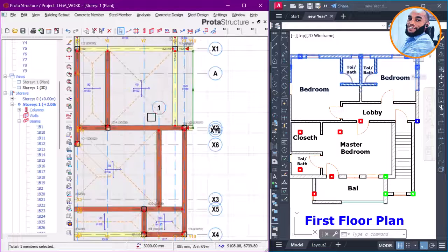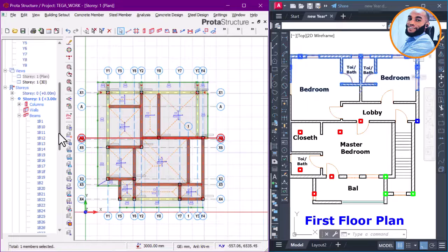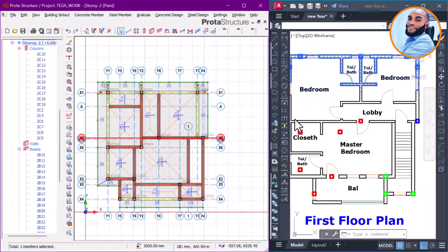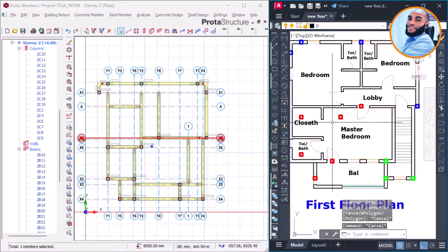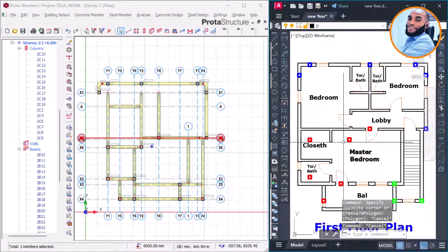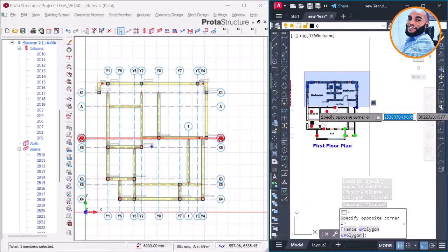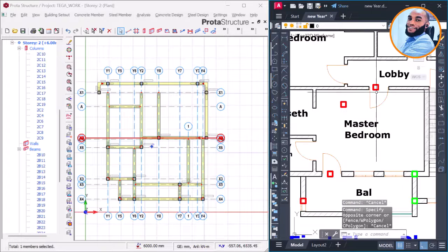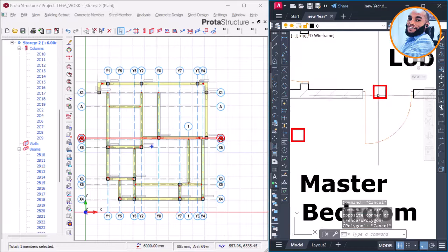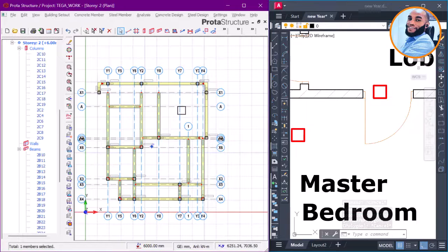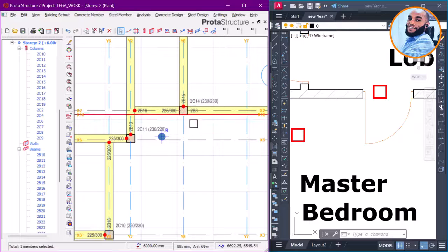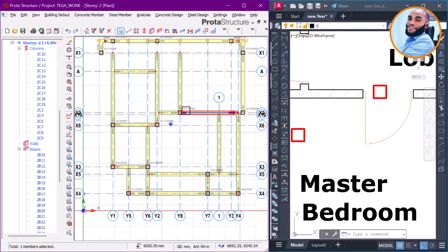Okay, so go back again right now to plan view story 1. Okay, so go to plan view story 2 first, because that's where we are going to do our changes. Okay, that's fine. Now on story 2 we are done with the column around this place. You can see that this one is appearing on the door area, which is this one here. So we need to remove it. Now don't just remove all the columns, else you get confused. Anyone you remove, make sure you have provided a support below so that you won't get confused.